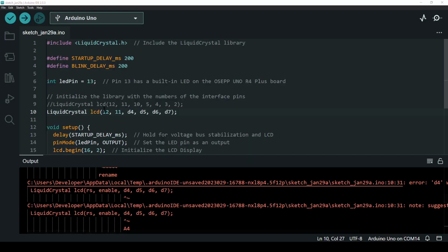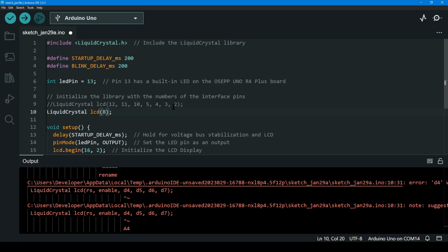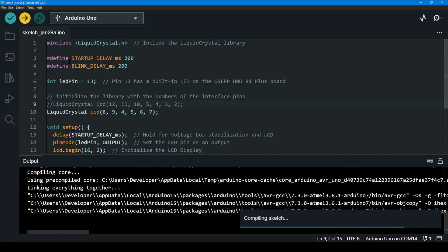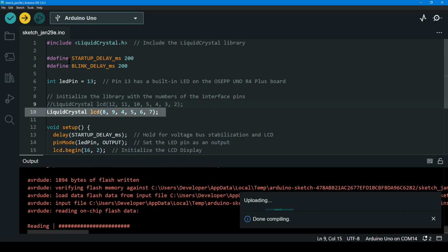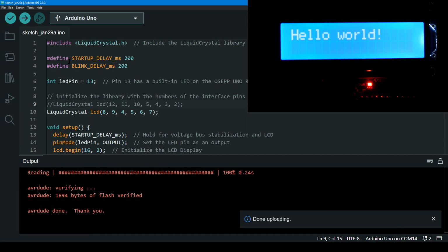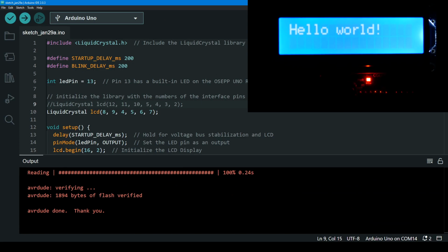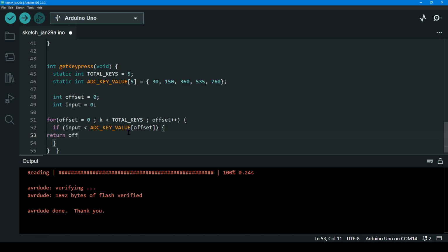While thinking about the code, I noticed there wasn't a specific header file called out for the display, which meant that there are no definitions to get the pins right. At a minimum, this style of LCD requires 2 control lines and 4 data lines. In this case, every pin definition was incorrect. Fixing this single line of code also fixed the problem. In summary, just watch out because connecting 2 outputs together, even by accident, can damage the microcontroller.